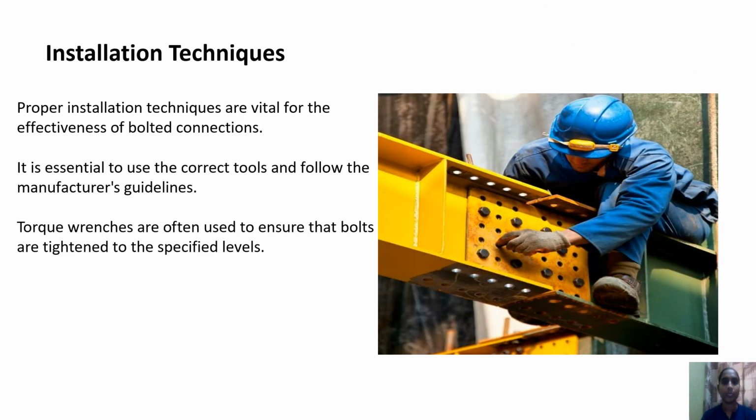Installation techniques. Proper installation techniques are vital for the effectiveness of bolted connections. It is essential to use the correct tools and follow the manufacturer's guidelines. Torque wrenches are often used to ensure that bolts are tightened to the specified levels.